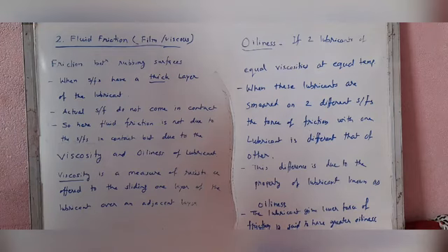The absolute viscosity of a lubricant may be defined as the force required to cause a plate of unit area to slide with unit velocity relative to a parallel plate, when the two plates are separated by a layer of lubricant of unit thickness.